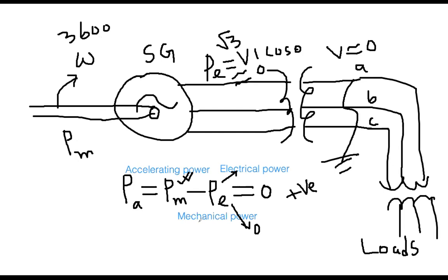So this is one situation. Then everybody see, for example, it is not the short circuit. The system was running fine. The Pm minus Pe was 0. What you did, so you are the customers. Here are the loads. Somebody suddenly injected more load. For example, you increase another 10 megawatt load in the system. So assume that your Pm was 100 megawatt and your Pe was also 100 megawatt initially. And then the system was balanced, the result was 0.